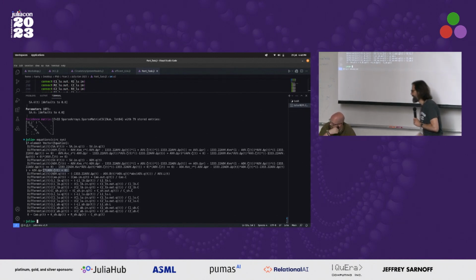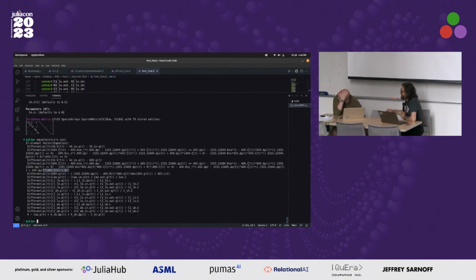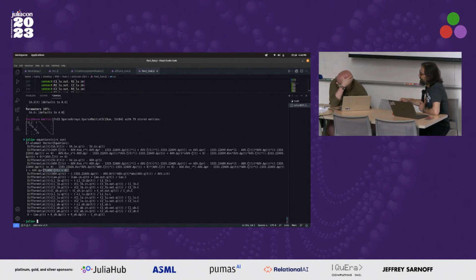I guess where I'm getting at is that usually with an ODE, you would want either to soften that discontinuity or put a callback there, like a zero crossing callback. We found that we don't need to do that in this case, because DifferentialEquations is pretty clever at shortening the time step whenever one of those internal changes happens. You don't need callbacks that often if you have these if-else statements in your code. If you do it by hand, then you have to put callbacks in. But it's all really transparent in this case.